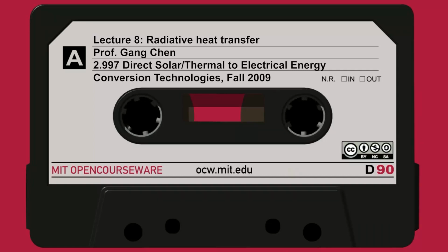Because the radiation from the sun is at a very small angle, it's almost low incidence. And when I write this emission, I'm writing the emissivity as isotropic. I could potentially design the surface emission only in the same angle where the sun comes from. Then I have to do an angular integration, and that probably could go even to a higher temperature than this, if I just make that guess. Okay?